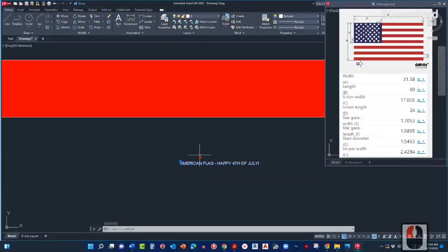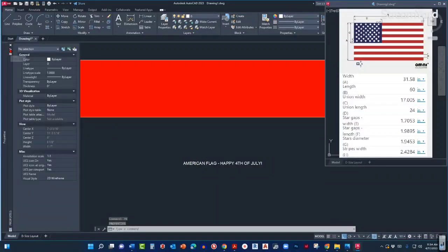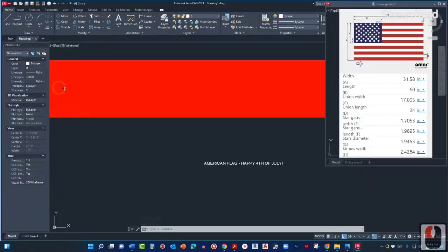We said 1 inch. So let's open the property palette. This is a new concept for you to learn that I'm glad we are explaining. So let's open the property palette using PR for properties. And then let's of course click over here to lock that.